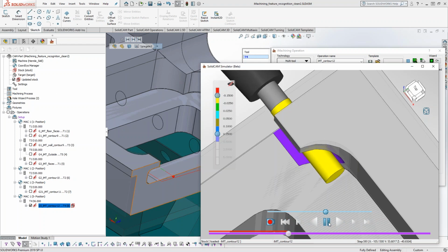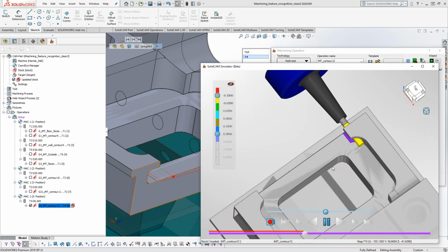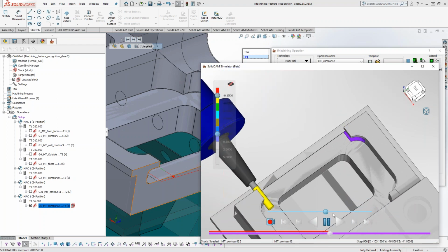Being able to see these things in here is helpful before you go out to the CNC and wonder why, if you start cutting and in the middle of the pocket it starts sounding different. You start getting, I don't know, a different chatter, maybe. This is a small tool, so cutting that deep, you could get some tool flex. So being able to see these things in the simulation before going out to the machine is just super, super, super helpful.